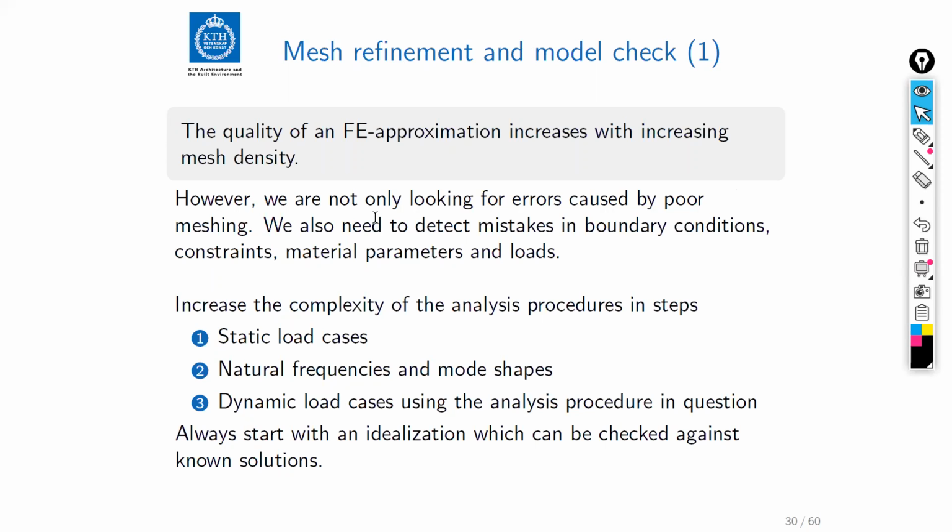But we need a strategy to deal with all the options and all the decisions that we have to make when we build a model. And the fundamental thing here to do is to start simple. Actually start with something like a simply supported Euler-Bernoulli beam, or something that we can even find a closed form solution for. And then we increase the geometrical complexity in steps.